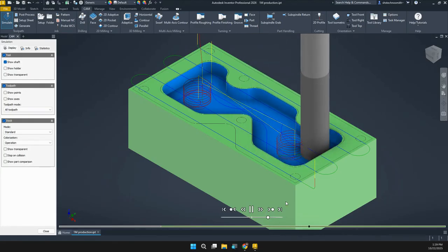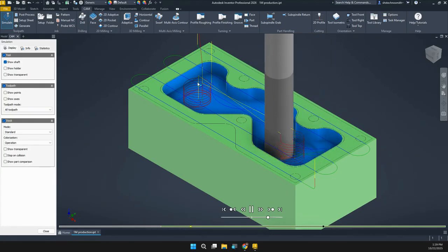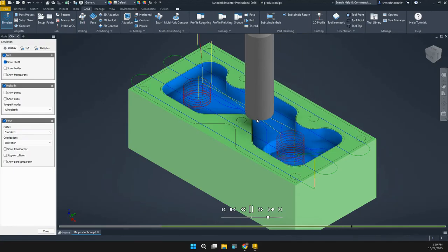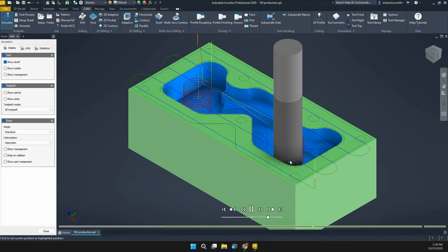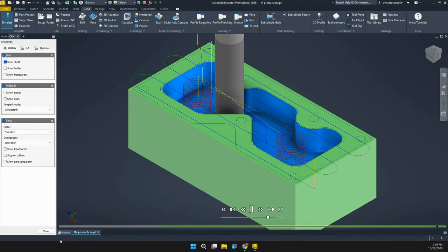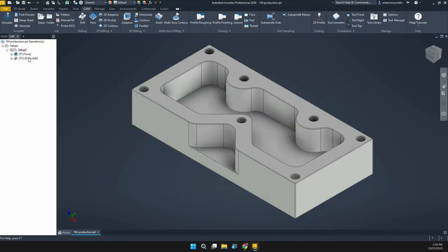So this is called a helix. That's the shape. The reason for that is because, unlike a drill, an end mill is flat on the bottom. And so if we're going into a very tough material, we want to try to only cut with the side of the teeth. So this 2-degree helix allows us to cut that. Now, we're not cutting aluminum or steel or whatever. We're just cutting butterboard, which is a polymer.